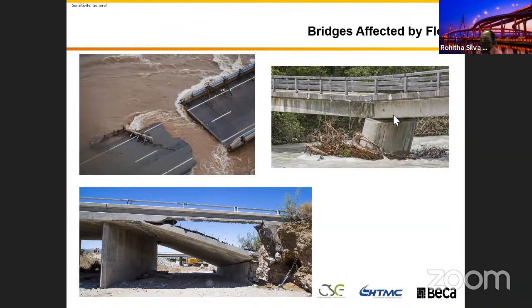It's really hard to restore this bridge rather than demolishing it. You can see the flood damaged the bridge embankment here. That caused the collapse of the bridge. So because of that, pay really big attention when you do the flood modeling and the design.